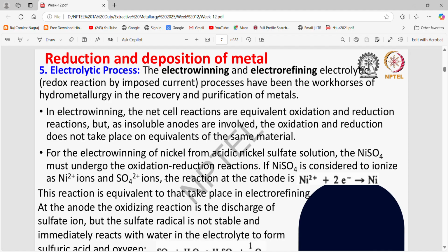The solution acts as an electrolyte solution, and we provide the anode and cathode with the voltage to complete the whole current cycle, so that current can flow from anode to cathode with the help of the electrolyte solution, and we can recover the copper from the solution.